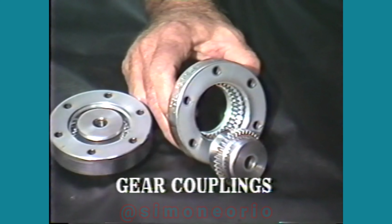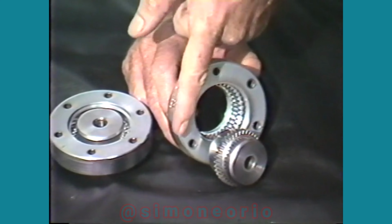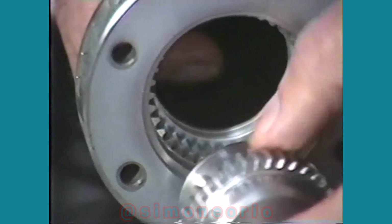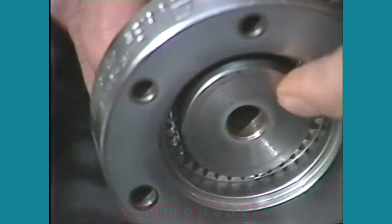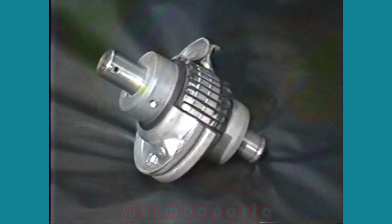Gear couplings. Here, hubs with gear teeth on the outside are surrounded by a 1- or 2-piece coupling body called a sleeve. The sleeve has internal gear teeth. Here, the tooth profiles of the hub teeth and the sleeve gear accommodates misalignment between the two parts. This coupling must be lubricated.